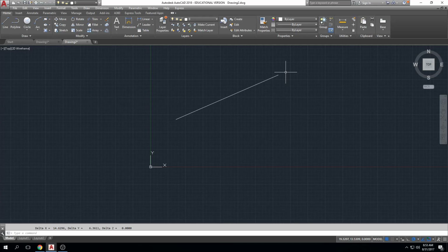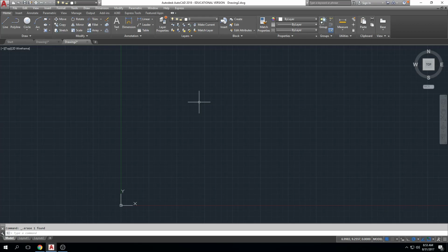But we're not too worried about this. We'll learn how to input these, and then we'll have it in our mind to understand AutoCAD. Okay, I'm going to delete this line, and let's talk about how to input some of our coordinates. We have 5 coordinate input methods we're going to talk about: absolute, relative, polar, direct distance, and dynamic.